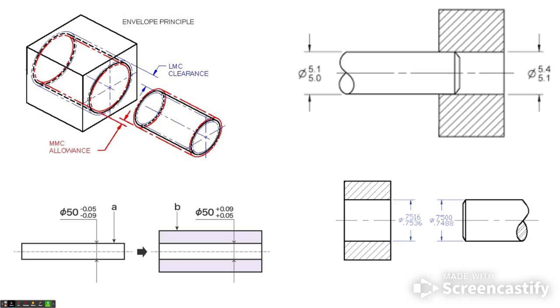And so with that in mind, oftentimes the designer or engineer has to design parts that fit according to the bearing or the gear that would be selected for that application. And of course, if it's a large enough company where you're able to cut your own gears and make your own ball bearings and your own shafts, then you have a little more liberty as far as how you tolerance these parts and what becomes important to you in that design.